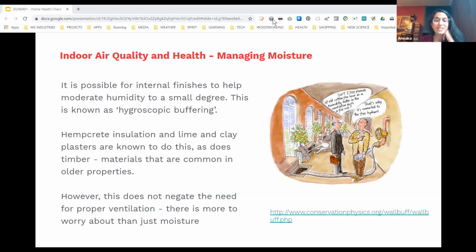Insulating: if you think about the idea that as air cools, the relative humidity goes up, and you might get 100% relative humidity, which is the dew point. So it'll be the coldest surfaces in your home, as you'll probably know, where mold grows. So doing things like insulating or making those areas warmer will make a difference.